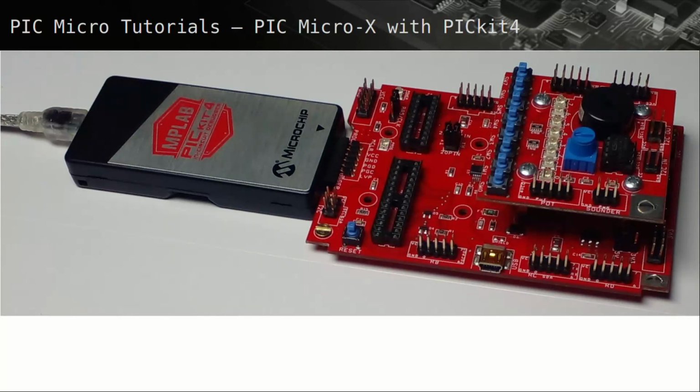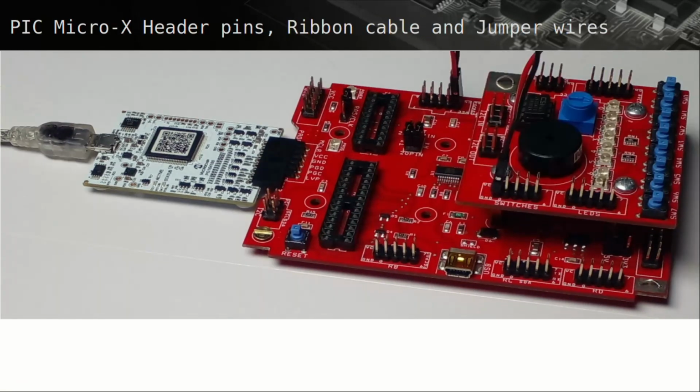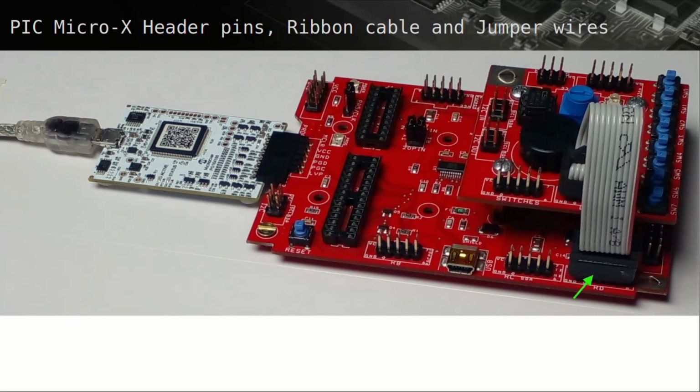The PIC Micro-X development kit is comprised of 2 boards, the main board below and the trainer board mounted above. Here the PICkit 4 is connected to the PIC Micro-X kit, and here the SNAP programmer is connected. Here is an example of jumper wires used to connect the main board and trainer board headers, which I'll explain shortly. I'll also explain how to use a ribbon cable to connect main and trainer board headers.